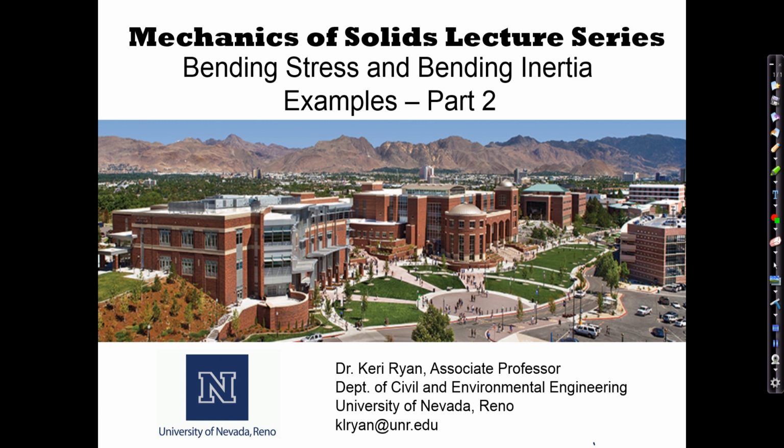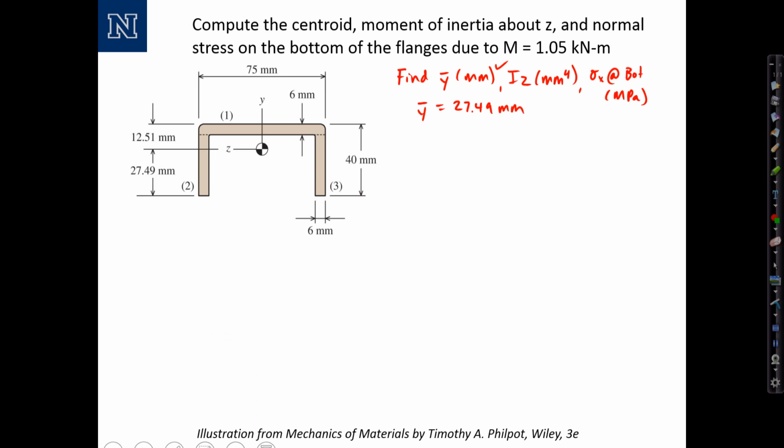In this series of videos, we're working examples calculating bending stress and bending moment of inertia. In this video, we're continuing a problem that we started in the previous video. We're asked to calculate the centroid, the moment of inertia about z, and the normal stress on the bottom of the flanges due to an applied moment of 1.05 kilonewton meters.